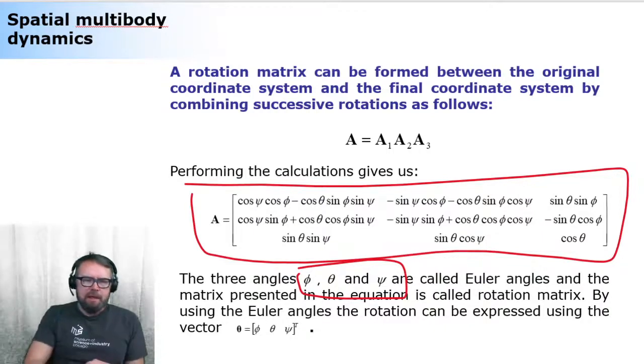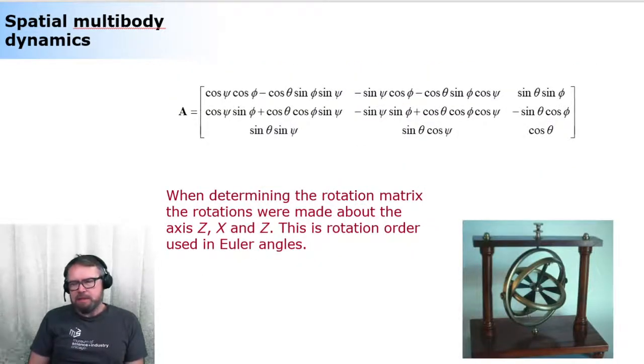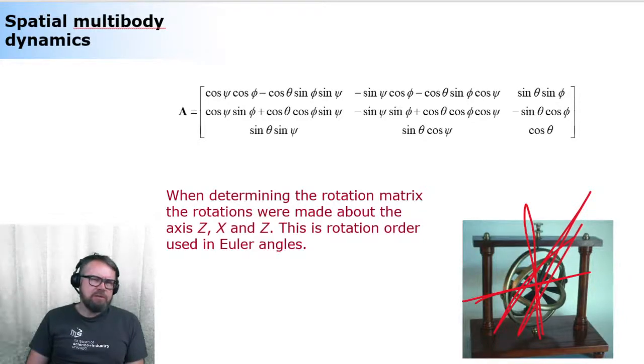All right? Where are these parameters typically coming from? Well, you see that there is this gyro here. My explanation is that these are typically used in a gyro as well. So they are like z-coordinate axis, x-coordinate axis, and z-coordinate axis. So this is where they could come from. This is very often used as a sequence of rotation. Sometimes you can see some difference, but it doesn't really make much of a difference in terms of mathematics. So whenever using 3 parameters, you have this mathematical difficulty that is associated with singularity.